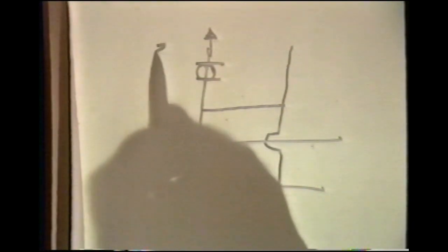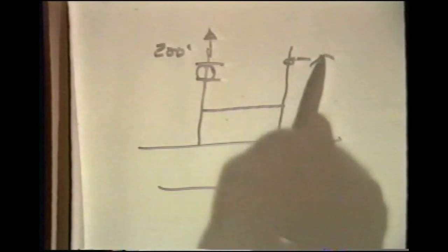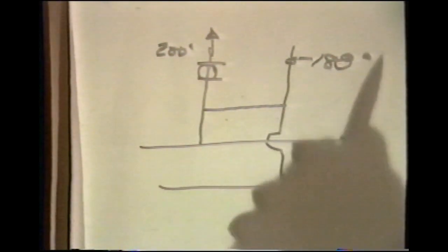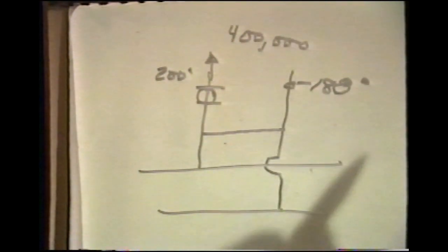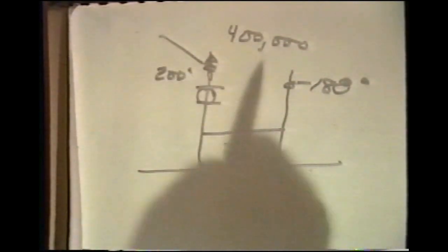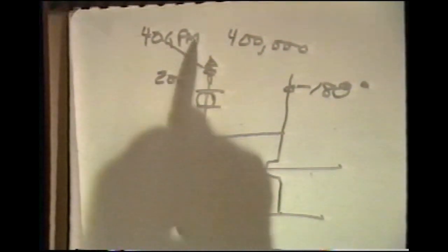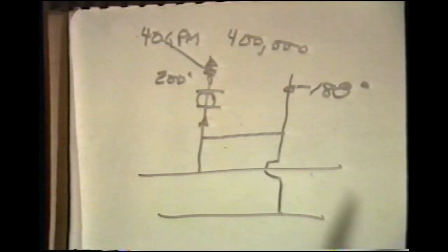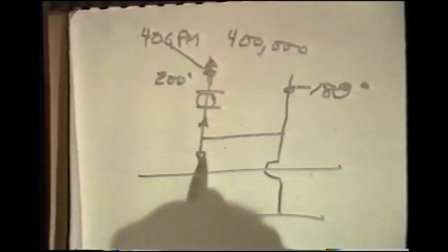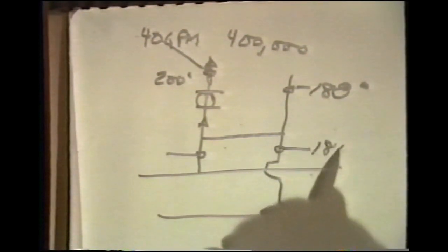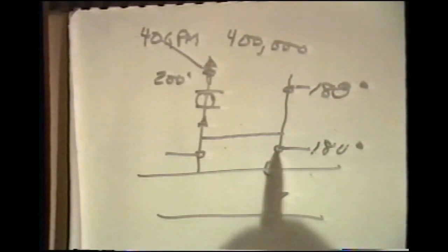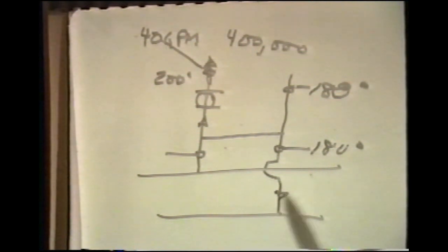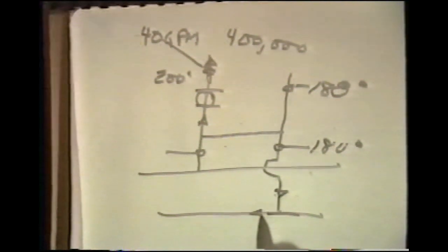Now we needed 200 degrees supply water, 180 degree return water, and had a load on the building in the range of 400,000 BTU. This established then a flow rate need in the building of 40 GPM. Now we knew we had 200-degree water temperature leaving and established that we did have a water temperature return of 180 degrees, which would occur under this circumstance because the return water temperature from the building circuit must match return water temperature entering into the basic return main.